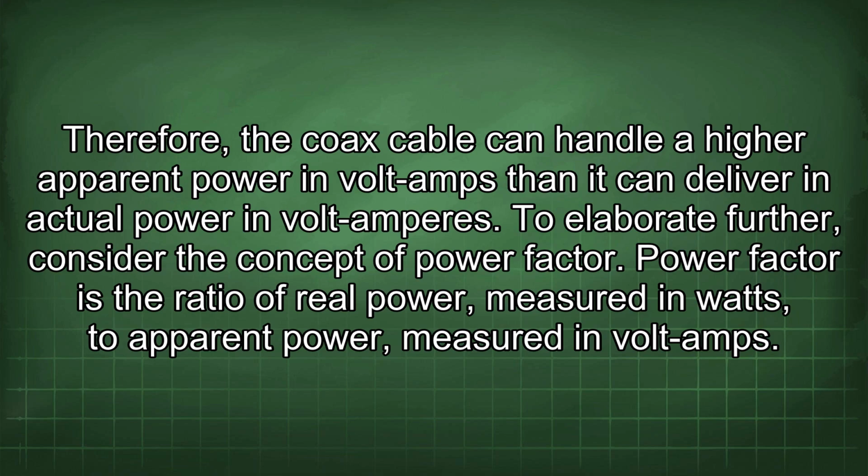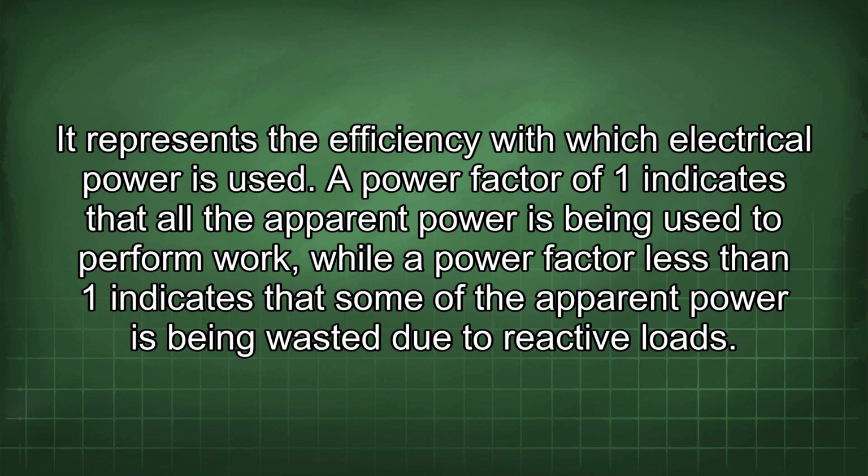Power factor is the ratio of real power, measured in watts, to apparent power, measured in volt-amps. It represents the efficiency with which electrical power is used. A power factor of 1 indicates that all the apparent power is being used to perform work, while a power factor less than 1 indicates that some of the apparent power is being wasted due to reactive loads.